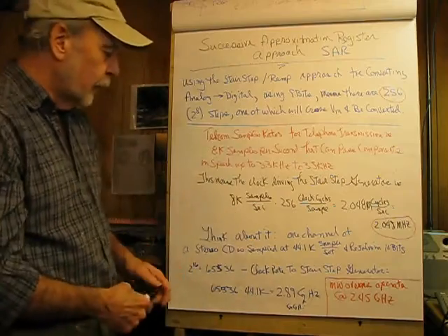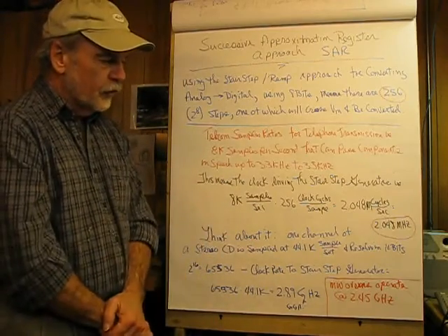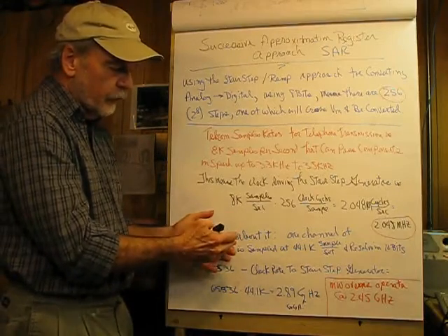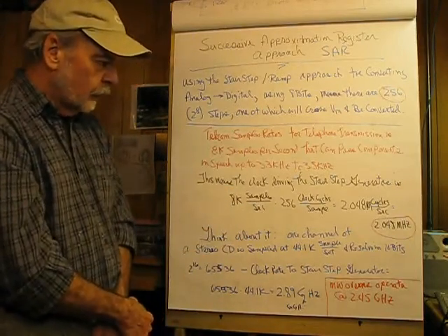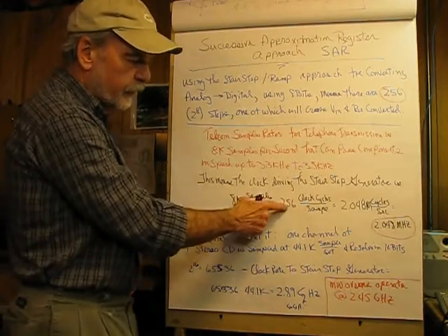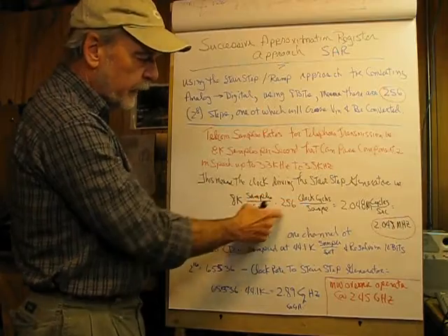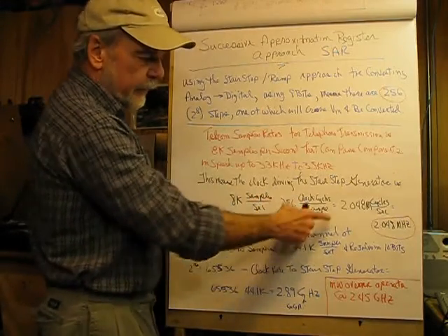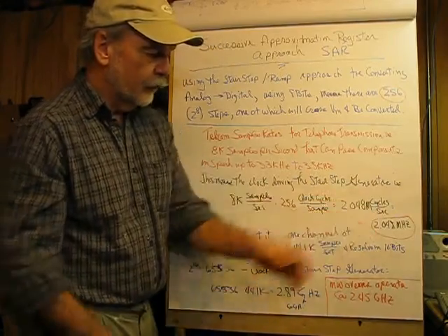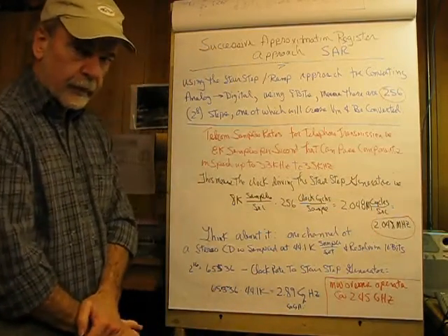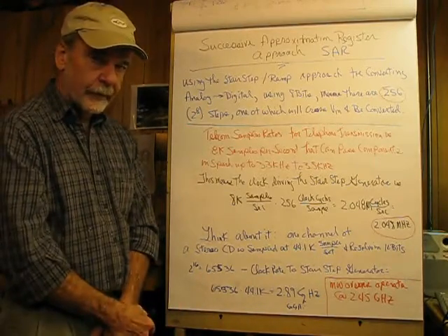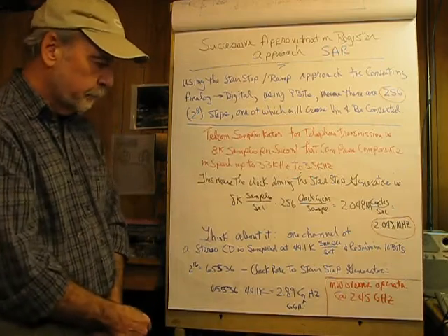But anyway, let's look at what this means from the standpoint of the clock frequency that's feeding our stair-step generator. If we have 8,000 samples per second and 256 clock cycles per sample, and we multiply this together, we get 2.048 megacycles per second. And that's going to be the frequency that's actually driving the up counter. That's pretty high frequency, and we're only talking about speech.